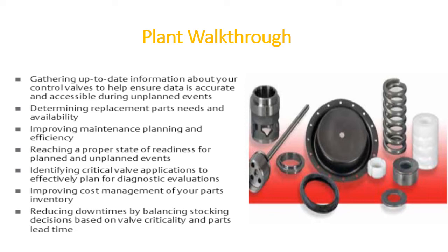So after you have all the data, you should plan which part is to be replaced, whether the soft parts need to be replaced or the hard parts need to be replaced. Frankly speaking, for about 80% to 90% of control valves, hard part replacement will not be required in their lifetime, which means around 15 years.